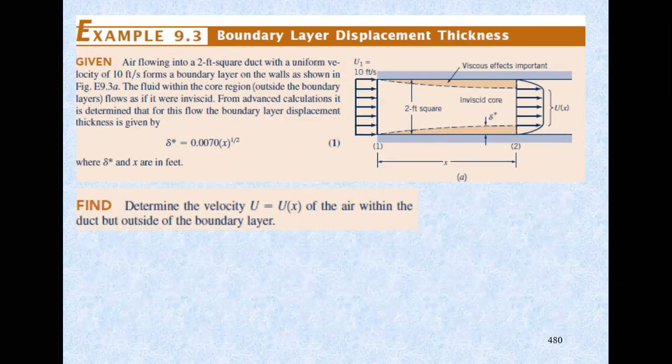Some of you may question why we didn't consider this boundary layer concept when we were analyzing the flow in a pipe, for example. Actually, we did. Although it's not done analytically, we actually incorporate the boundary layer effect into the friction loss, or the major loss, HL.